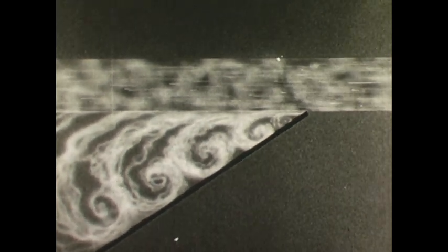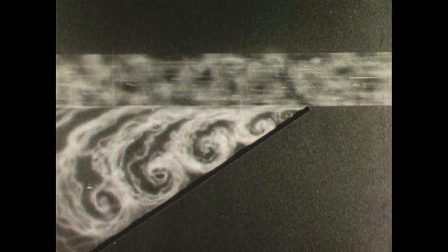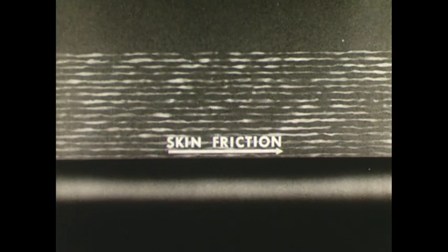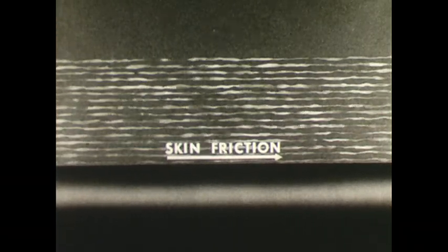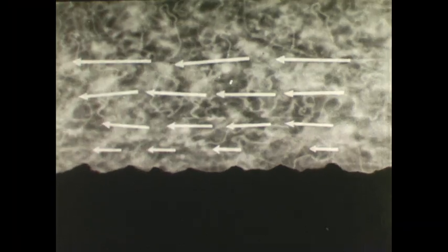Turbulence is one of the two principal factors opposing the useful employment of an airfoil. The other parasite factor is termed skin friction, or surface resistance to relative motion. Highly magnified, the best possible surface has irregularities from which air particles rebound into the airstream, colliding with other particles, setting up friction and interfering with these flows, thereby opposing the relative motion. This opposition can never be eliminated, but can only be reduced by using the smoothest surfaces possible.